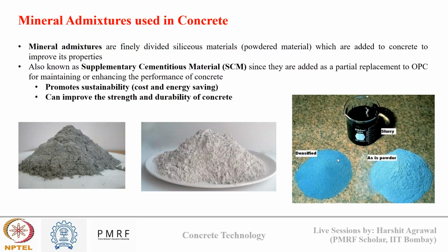So last week we concluded the fourth week of the course, where we talked about mineral admixtures used in concreting. Mineral admixtures are also known as supplementary cementitious materials and are used as a partial replacement of cement to promote sustainability and improve strength and durability.